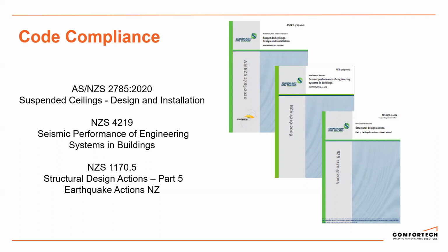And then another one that we often forget about is NZS 4541, which is your automatic fire sprinkler systems. So this covers the design of fire systems, defines bracing requirements for sprinkler system and pipe work. And this is important when we're looking at clearances and plenum spaces.